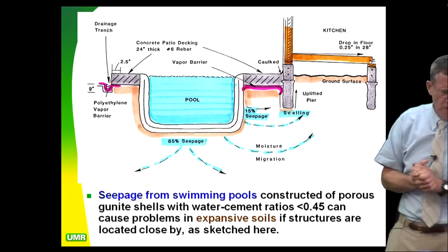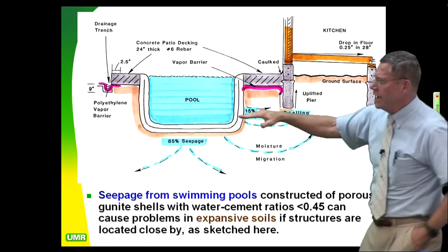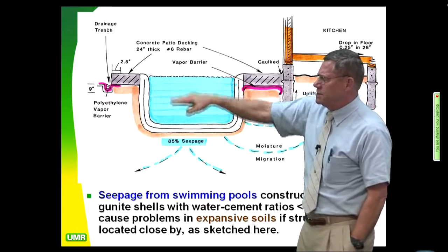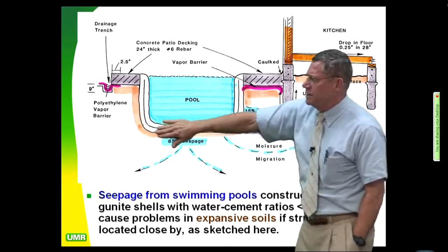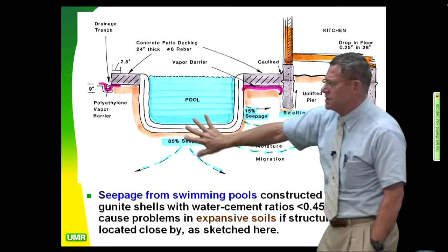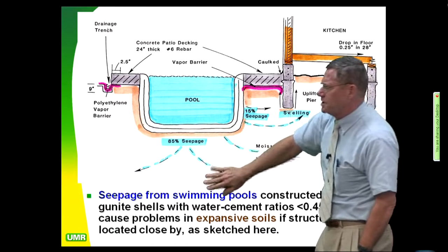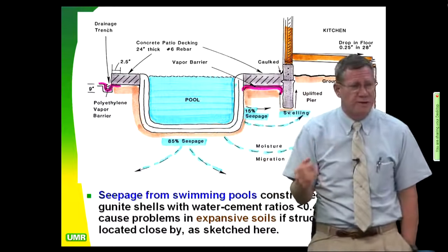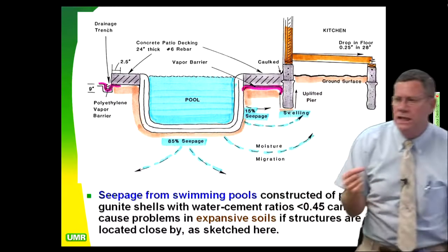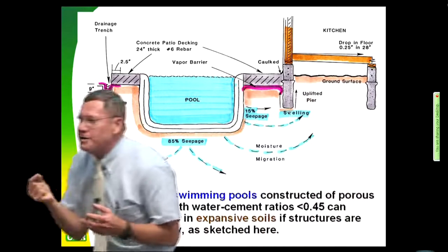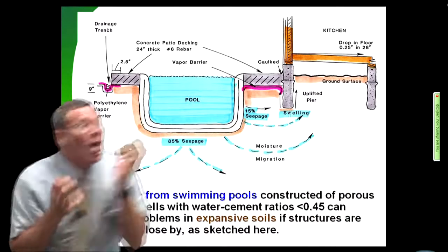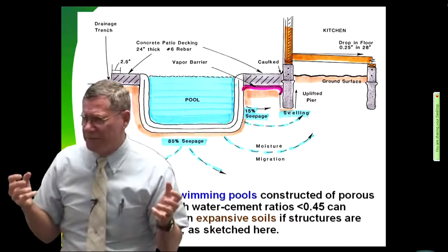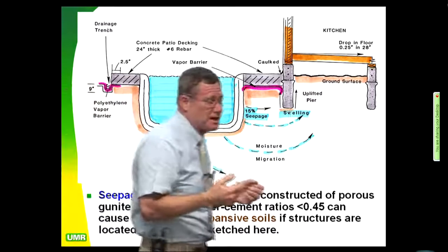And what you have here is more hydraulic head in the middle of the pool. So 85% of the seepage is right here. It's out the bottom. So it's going to go down, and this is partially saturated down here. So it's going to go down and be chemically adsorbed, with a D, adsorbed. Clay loves to take water, just like the IRS in your paycheck. It never gets enough. It's just eating it up, eating it up, sucking up that water.